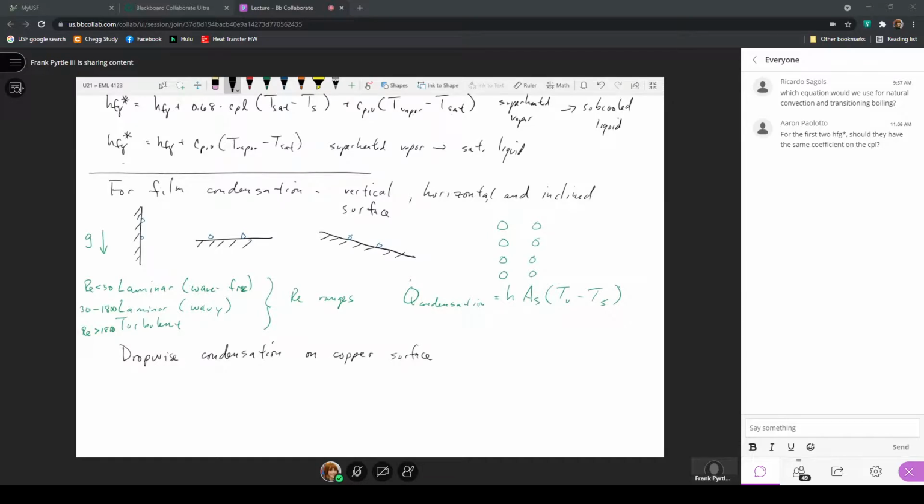text. The heat transfer coefficient for dropwise condensation is 51,104 plus 2,044 times the saturation temperature, when that saturation temperature is between 22 degrees and 100 degrees.